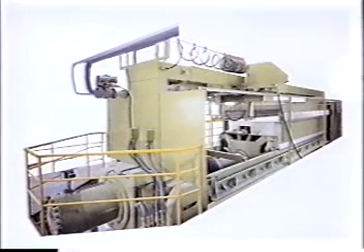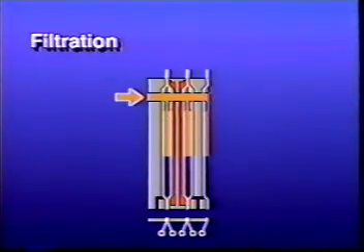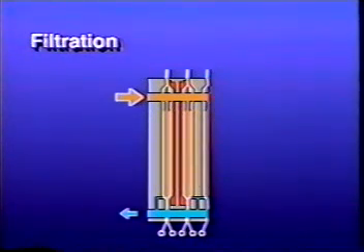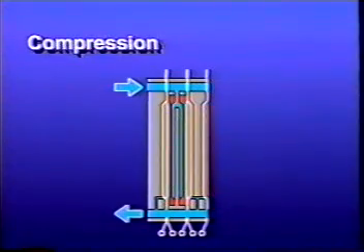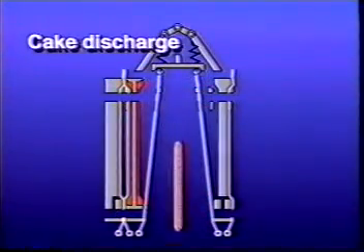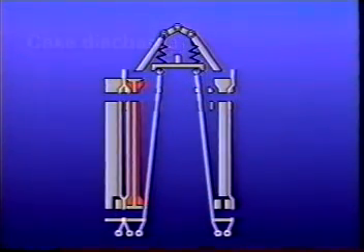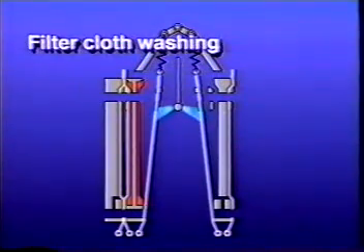The Model PF has a unique filter cloth suspension device for its fixed filter cloths. Similar to the UF, it is a top feed type. By employing a separable feed port protector, the filter cloths can be vibrated over their whole filtering area, enabling complete cake removal. This top feed filter press is capable of high pressure compression up to 25 kilograms force per square centimeter.